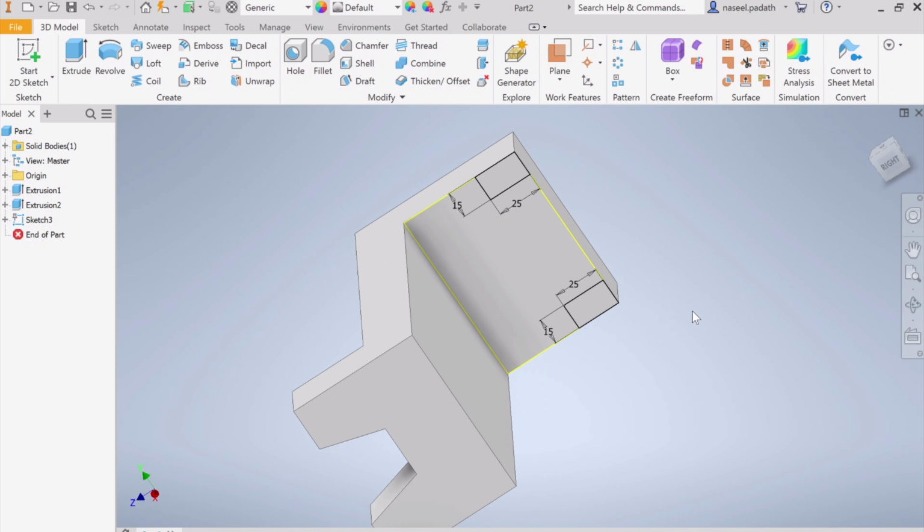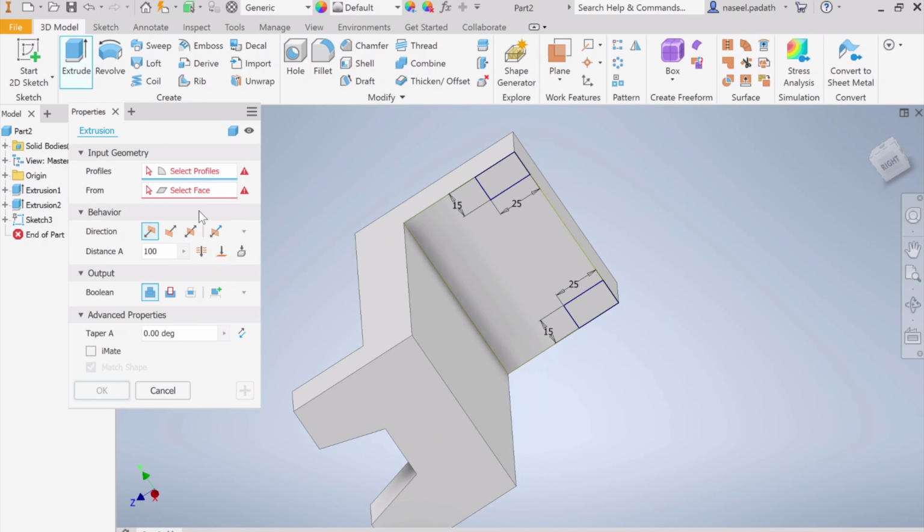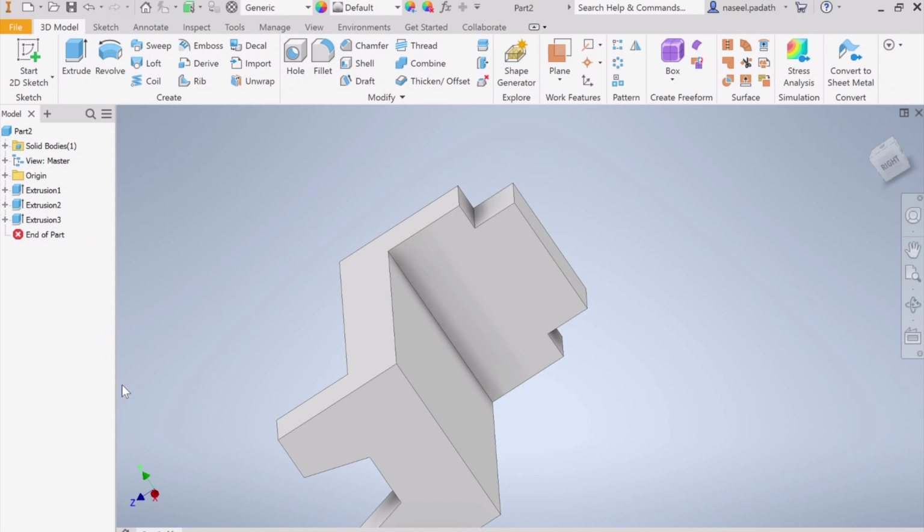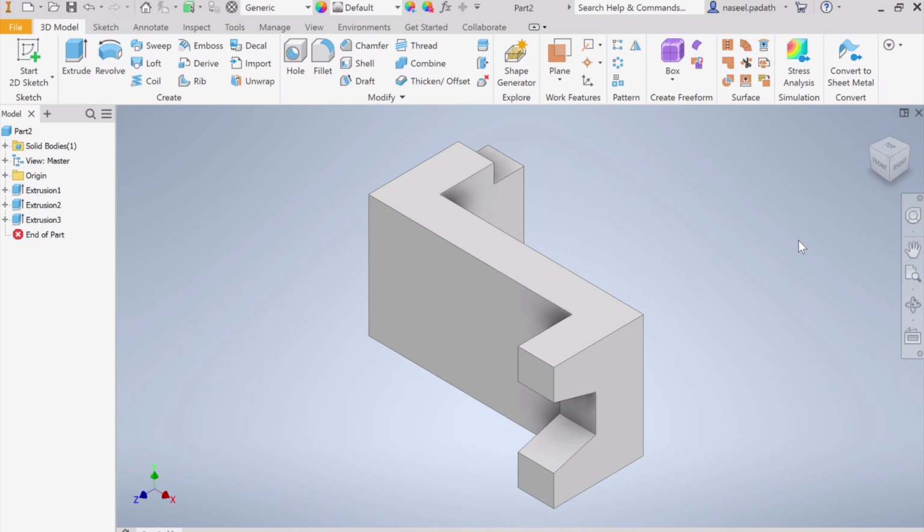Now we can make extrude. Choose extrude or hit E on your keyboard. And now I'm going to choose this profile. And what happened? It's generating the solid. Why? Because we didn't choose the cut option. Choose the cut option and choose this solid as well. Now it's cutting. Even though you click OK, it will not make any trouble, because on the back side we don't have any solid, but make it the standard practice. Always choose through all. We don't want to mess up with anything else here. So we are done with this cut and click OK. That's it. We managed to finish.